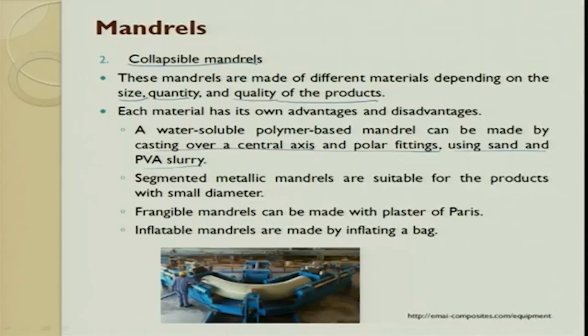So, look at this, this is a filament winding process tube wherein it is bent. So, here are some of the mandrels which are used for making all these structures, and the inside of this mandrel can also be made of a thin tube filled with pressure, so that it brings in the stiffness. Segmented metallic mandrels are also available today for making small parts. Fragile mandrels are also made out of plaster of Paris. Plaster of Paris is easy to make and good form can be done easily.